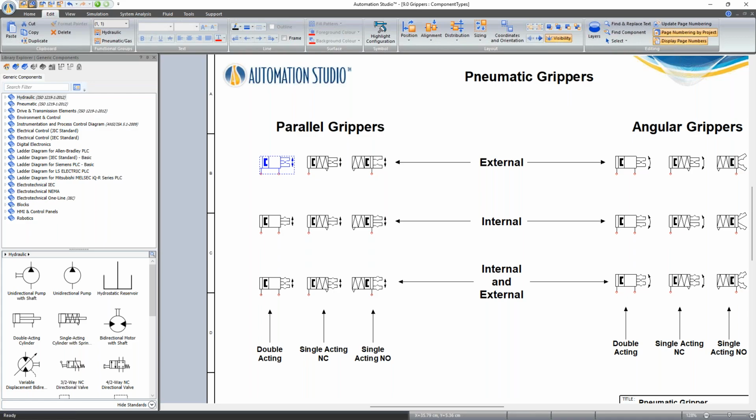Actually, usually we use them to control motors. For example, in the next version, we will support the BLDC motor, and the control of the BLDC motor is based on the Hall effect signals. They can help us to determine the relative position, so we can adjust our output signal from the controller.